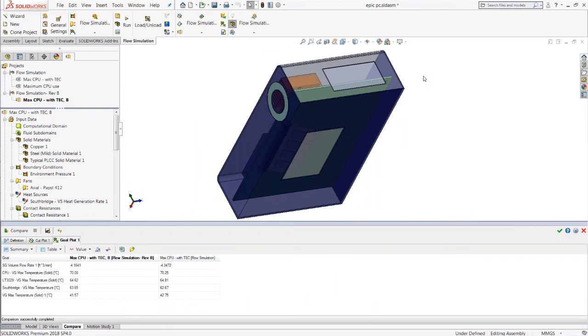So we could have done an external analysis which includes some of the airflow around the box. And in that case, we would have wanted to actually leave the vents themselves modeled into the case, whether that was a slot pattern or let's say a hole perforation or whatever. So an external analysis will definitely take longer to solve because of that, but it will be a little faster to set up because you won't have to do the lids, and it will be more accurate too.